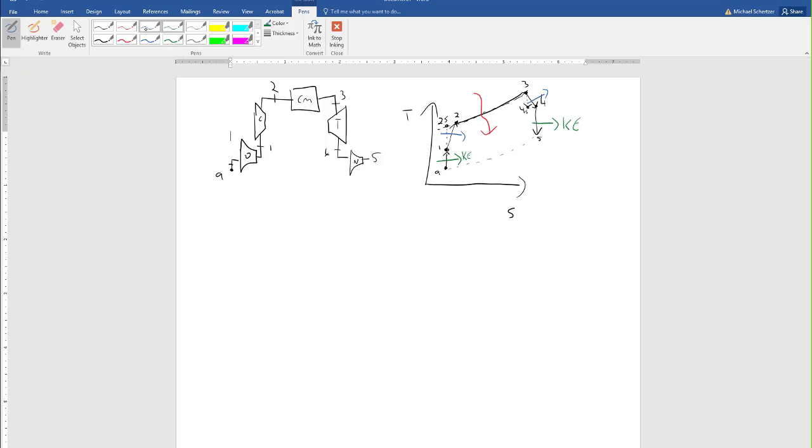And the other thing I'm going to do is remind myself up here, because this is the thing people often get wrong. I'm going to say back work ratio is equal to 1. And another way that I can do that is I'm going to draw a constant pressure line here and a different constant pressure line over here. So pressure at 1 and pressure at 4 will not be the same, which is different than a normal Brayton cycle.